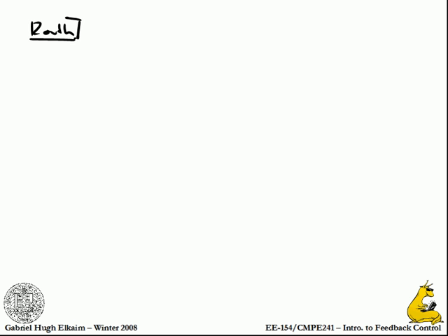Check in the book because it's a little more clear, but I'm pretty sure that in your Routh array you're going to have something like 1, 3, and then -1, 0, something like that. But the question is whether this is another sign change. I would say that based on this, you have 2 poles in the right half plane. So you get 1 sign change for one, the next sign change gives you the other.